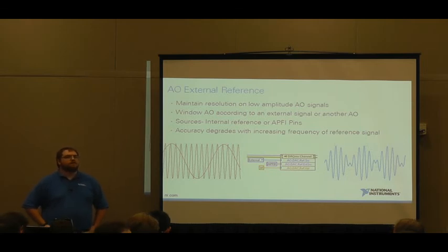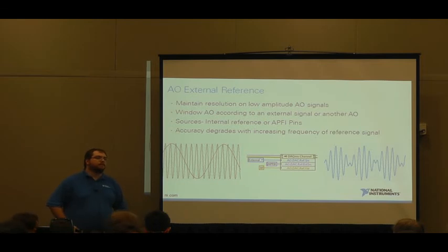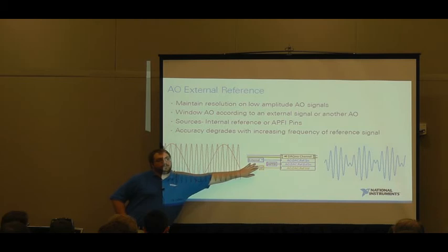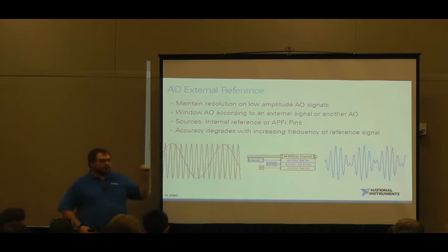It doesn't actually care that your analog voltage matches what you're saying, right? It doesn't care that it matches what I've set here, because this is just used to scale the data. Right. So if I set an analog reference of 1 volt, and I try and program a 1 volt output, I need to set my digital value to full scale so that my digital to analog converter passes out a full scale value that I know should be 1 volt.